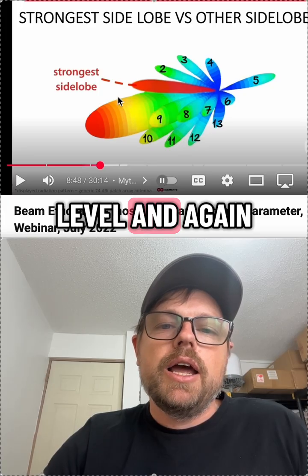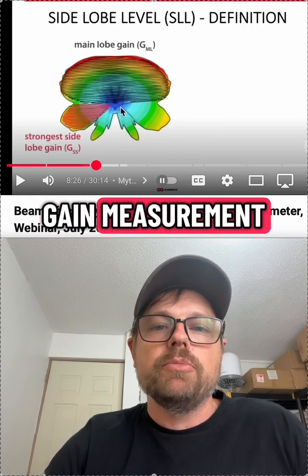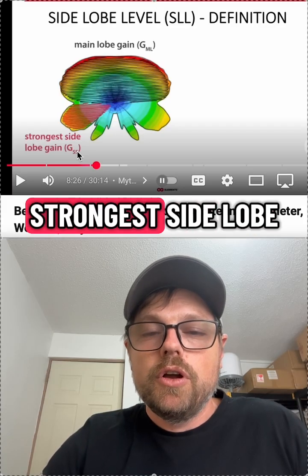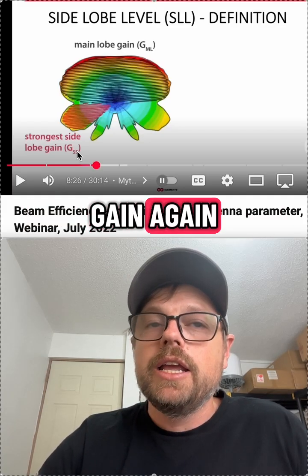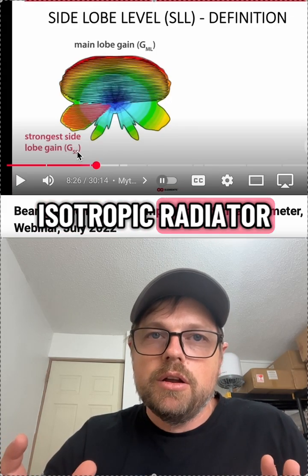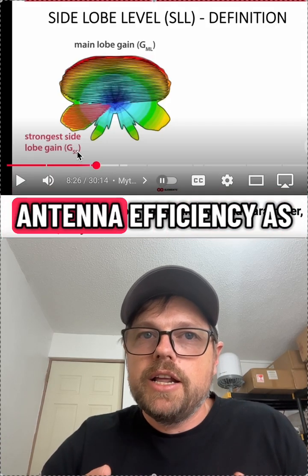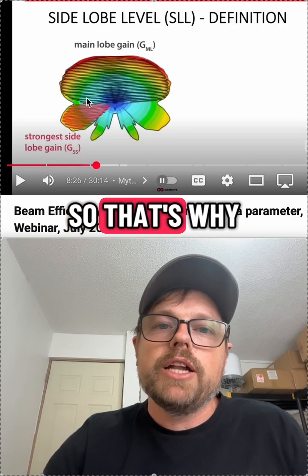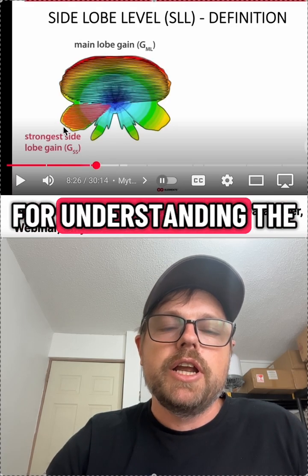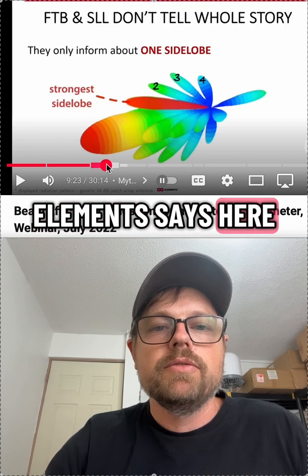And again, this is a gain measurement. It's the gain of the main lobe versus the gain of the strongest side lobe. Gain, again, is relative to a perfect isotropic radiator. So it is also built in measuring antenna efficiency as well. So that's why side lobe level is a very good antenna parameter for understanding the side lobe performance of an antenna, despite what RF Elements says here.